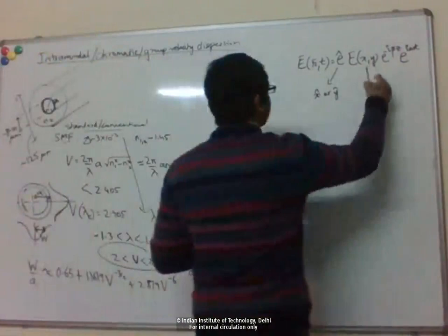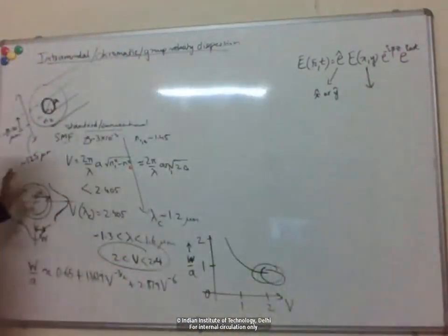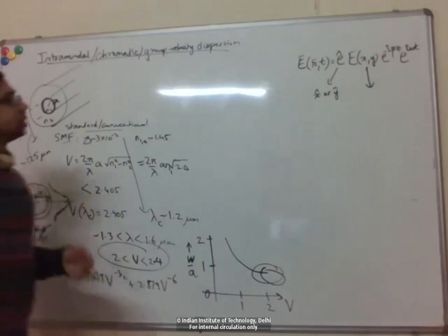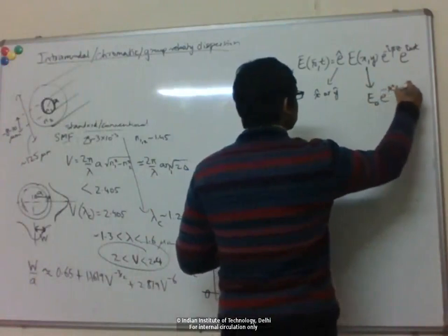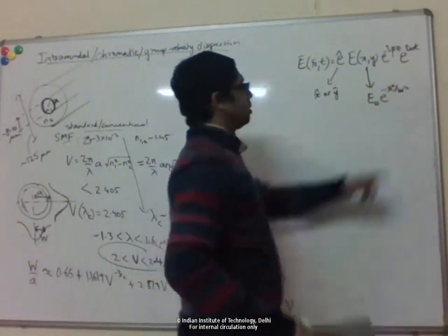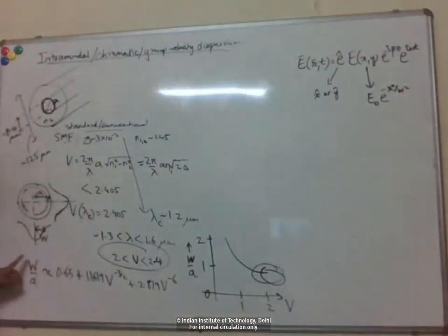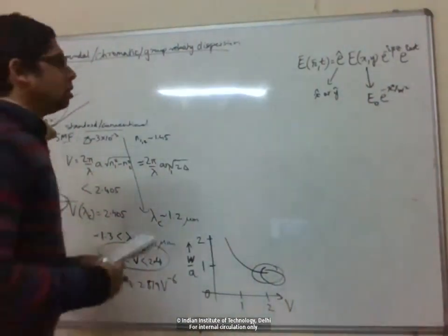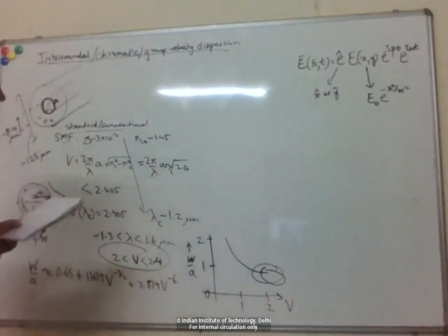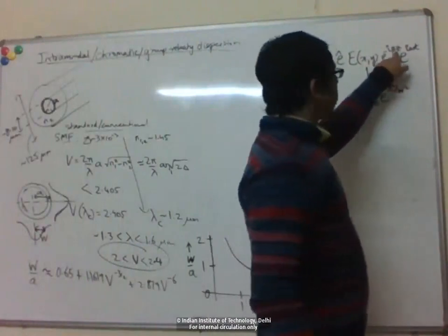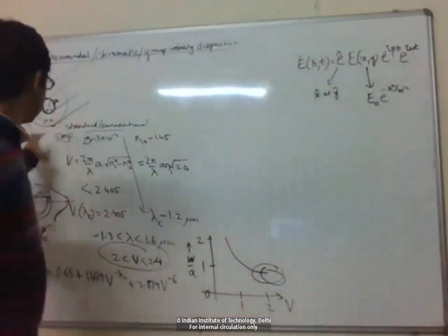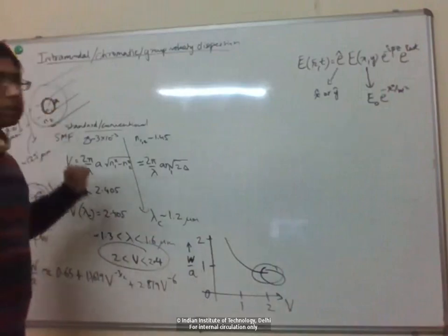For these LP modes, the exact mode profiles are Bessel functions, but the lowest order LP01 mode profile can be well approximated by a Gaussian, where W is again the mode field spot size. And this beta, recall, is the solution to the wave equation with this geometry and boundary conditions.